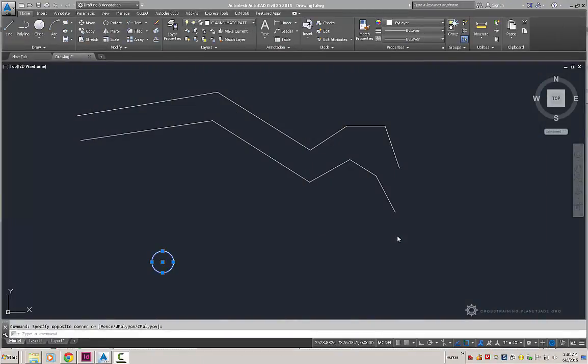So what we would like to do now is figure out how to specify a point, tell Civil 3D the length to the next point, and at what angle from the starting point. So let us first take a look at our drawing settings, because recall 0 degrees is north for this particular example.